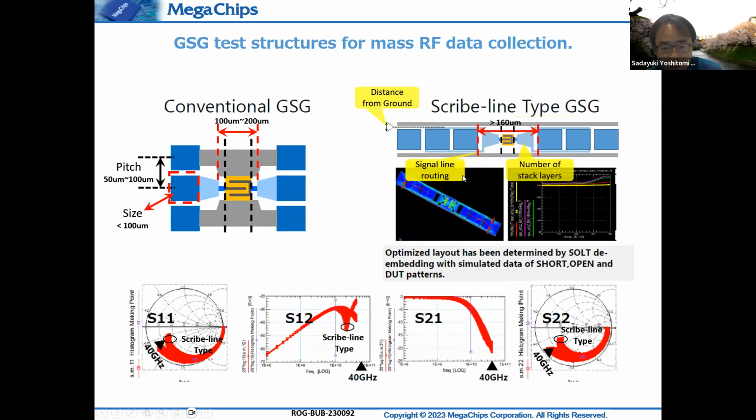So to optimize this kind of layout, we used electromagnetic simulations to optimize this pattern in order to have results as compatible as conventional GSG patterns.